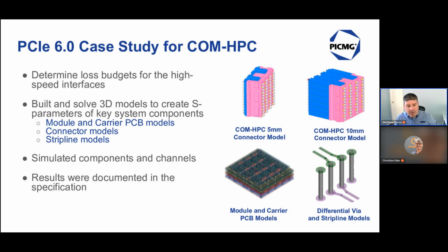The signal integrity design work is captured within the COM-HPC specification and also the COM-HPC carrier design guides. For the next few moments, we're going to extract some of that detail to talk about how COM-HPC modules, whether a client, a server, or a mini, currently can support PCI 5, but also how there's a roadmap to PCI 6 when that's enabled within the chipsets available from the semiconductor vendors.